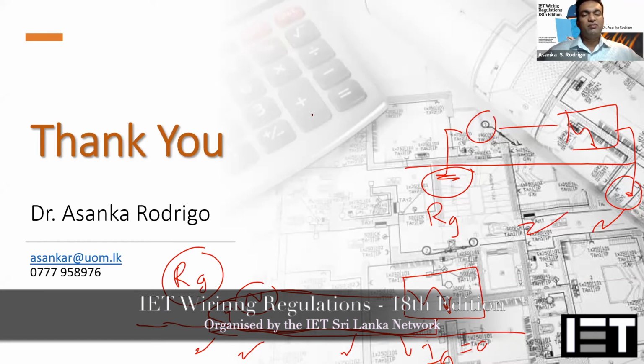Maybe there can be certain influences for you because you have a copper cable after the fiber router. From that one to the other location, you have certain copper cables running, even for your telephone system. Inside the house is copper cable. So there can be certain induced voltage in the copper cable, which can travel back and damage your equipment. Even if you disconnect, because obviously, as the SLT person said, there is no way of surges coming in through the fiber optic.